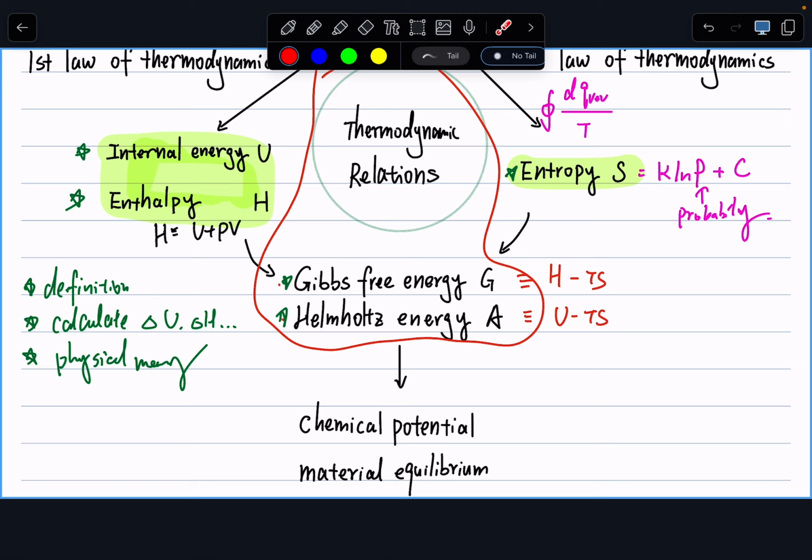Now this one equals Cp over T, and my dS over dP at constant T equals negative dV over dT at constant P, which equals negative alpha V. So if you don't remember how that's being done, you want to go back and review your thermodynamic relations and try to do that again, from the very foundation, so you know how that's being derived.